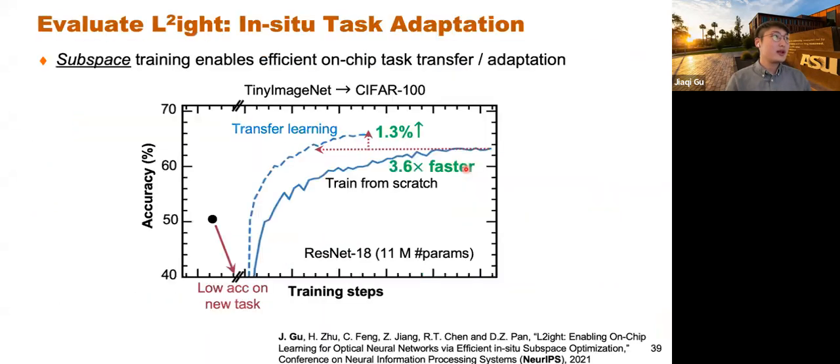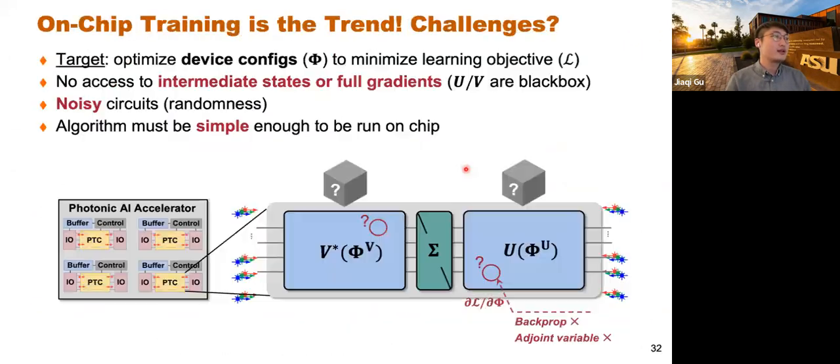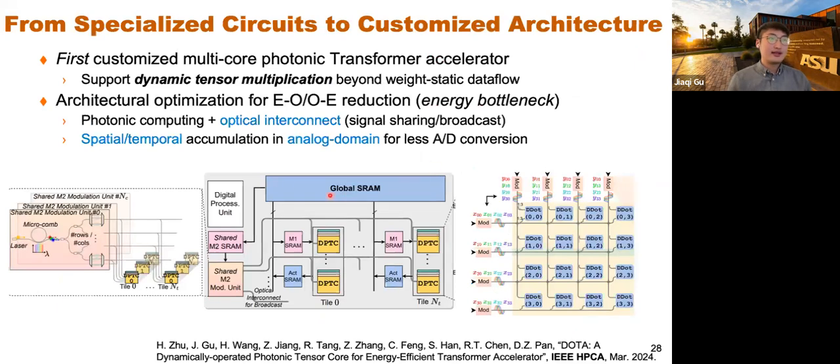Yeah, sure. Probably I can show the architecture, including all the components. For example, you have the memory hierarchy: off-chip DRAM and on-chip SRAM, with global and local buffers to hold the activation and weights. You also have the interconnect for signal communication and data movement, and the data flow and the computing part. Indeed, the memory is the bottleneck. With large language models, computing is not the bottleneck. It's always bottlenecked by memory, and the data movement through the interconnect is also a bottleneck.